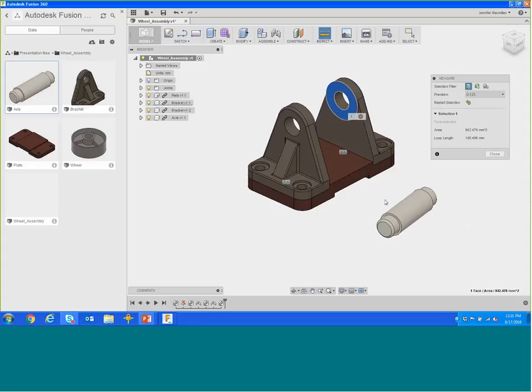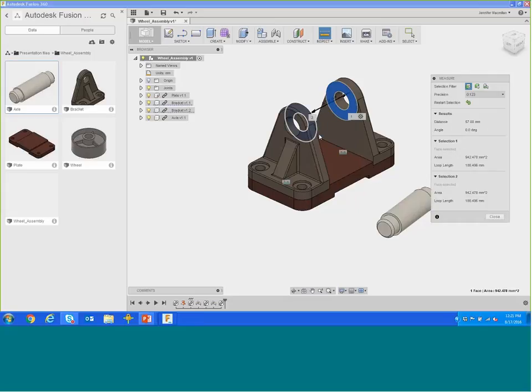And one thing that took me a bit to figure out, so I definitely want to give you guys a tip here. In Inventor, if you hover over a hidden surface, it will automatically bring up the Select Other tool so that I could pick that hidden surface. With Fusion 360, you have to hover over it, but then you have to press and hold the left mouse button. So I've just done that, and then I can scroll down and scroll through and pick that inner face.